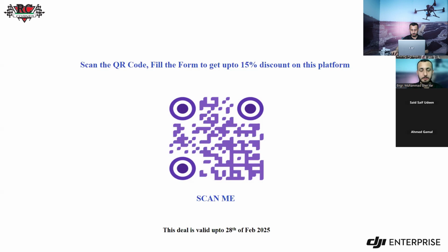I'm asking about the explosive which you are using. It's not in the list on the Strayos platform. I'm entering it manually, but it didn't succeed as a brand, as we use here in UAE. We're using some explosives, for example ANFO, at 0.8 density, and in the platform it's 0.9 and 0.85. So is it easy to put this explosive manually in the platform and use it always, not only for one or two projects, to keep it always there in the platform?